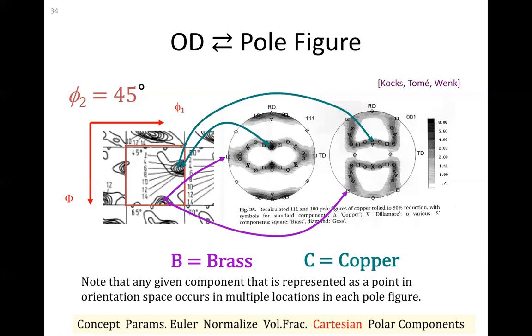that rotation. So if I only look at, say, the 001, there's an infinite number of ways I can have a crystal with an 001 axis pointed this way, all the rotations about it. But if I take 2 points on 2 different pole figures, any of those 2 points will correspond to 1 point in the orientation space.